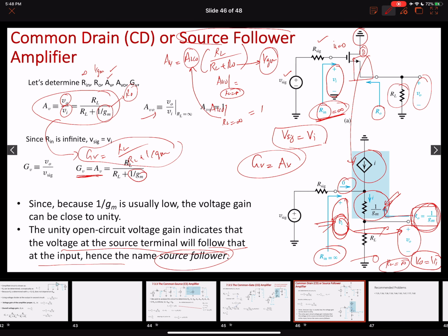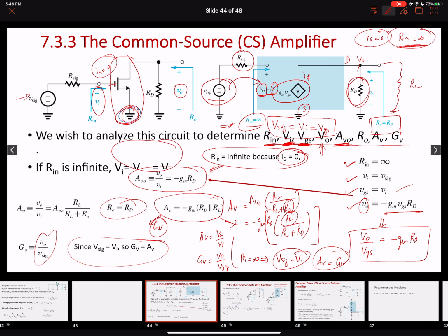Okay, so this is where we will end our lecture today. In today's lecture, we talked about different configurations in which we can use an NMOS or a MOS transistor to develop amplifier circuits. We discussed common drain, common source, and common gate amplifiers. Importantly, we derived all of these expressions of the voltage gain of an amplifier: open loop voltage gain and overall voltage gain.